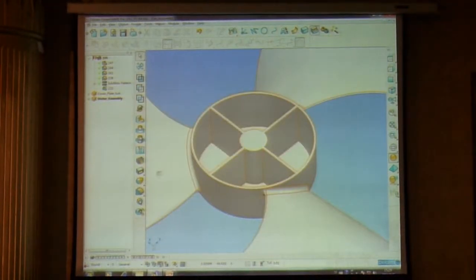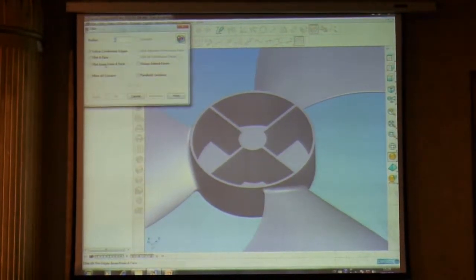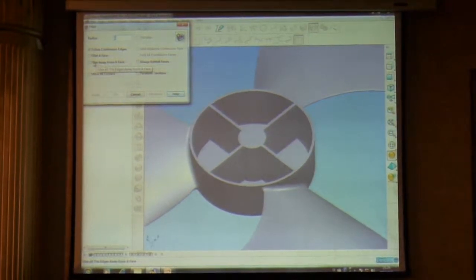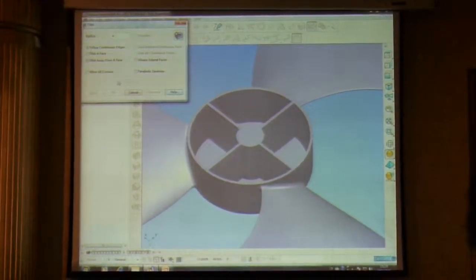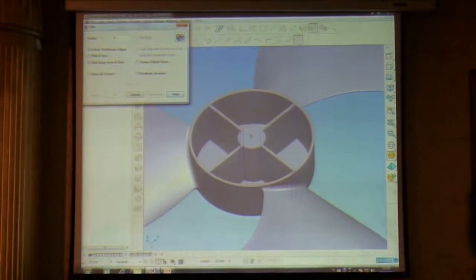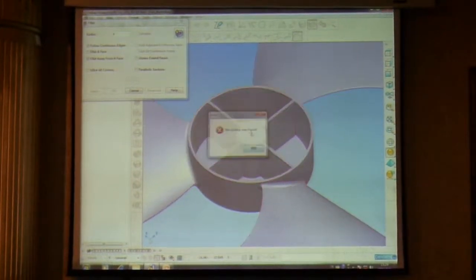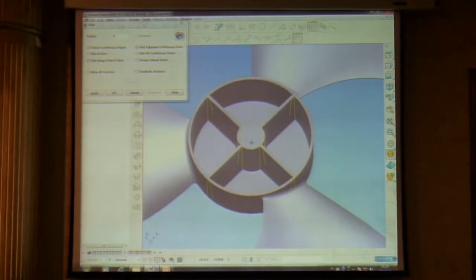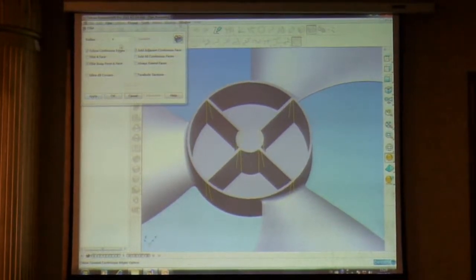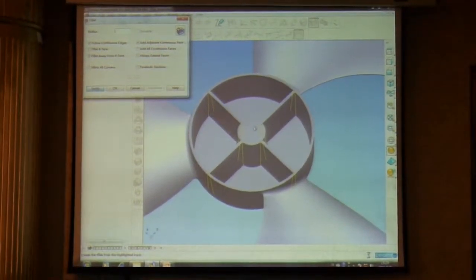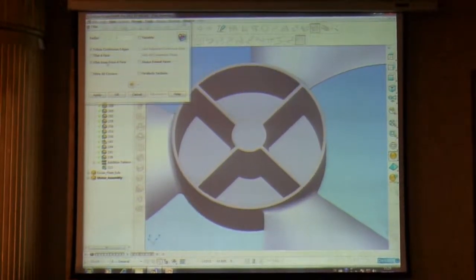Again, I have sharp corners that need to be removed, so I'll perform a fillet operation. And we have some nice tools with solid filleting. So for instance here, I can pick a single face of the solid, and you'll notice that multiple edges are selected in one go. So in this case, we create 16 fillets with one single mouse click.